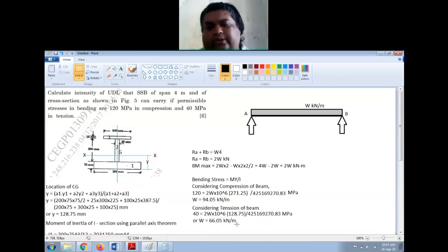Now if it were the other way around, if considering tensile stress the load is more, and considering compressive stress the load is less, and you apply the tensile load, the beam section below the neutral axis, which is subjected to tensile stress, will not fail, but this portion there will be compressive failure, right?